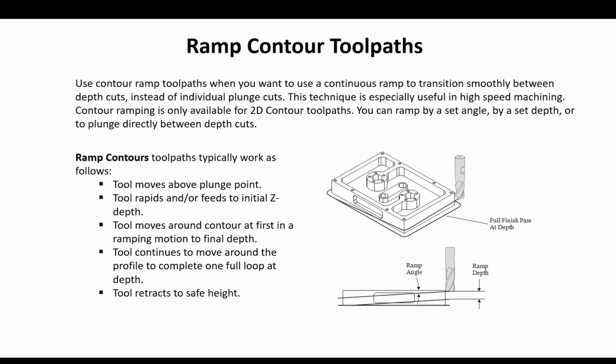Ramp contours are used extensively in the woodworking industry. They save stock material by doing away with planar lead-in moves, allowing parts to be spaced closer together.